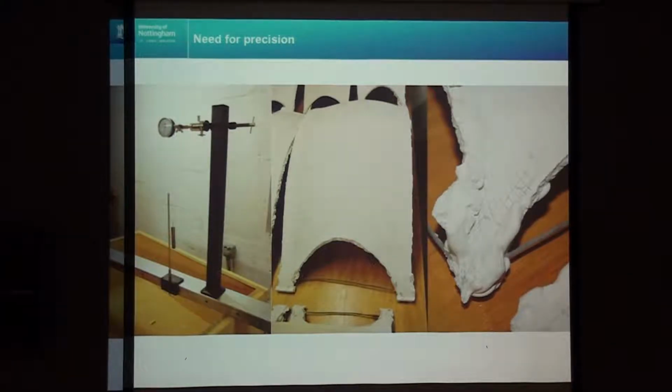And using a system, this is sort of a balanced weight system, he can measure to 0.01 millimeters. So he's measuring to 100th of a millimeter because he's scaling up from that up to 50 times. But even then, he's measuring effectively to 2 millimeters on the final structure. And the density of the grid is less in the center here and gets greater towards the corners.